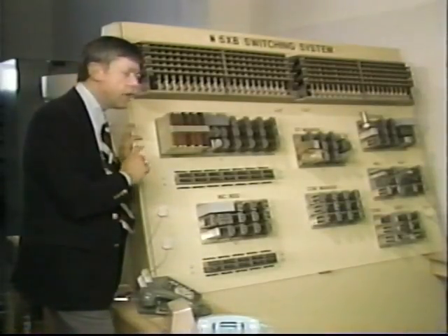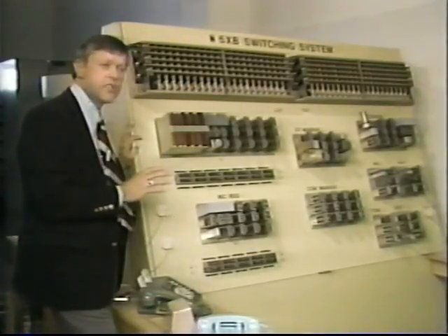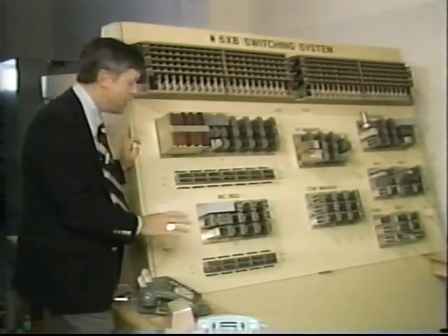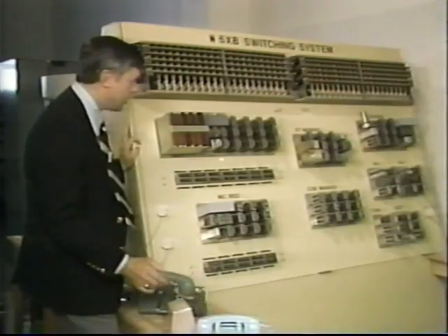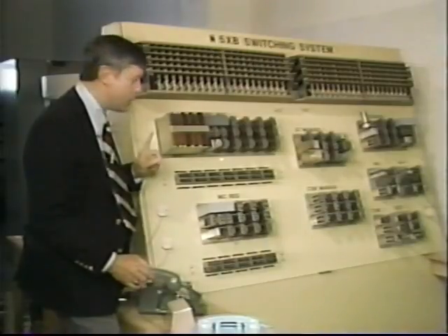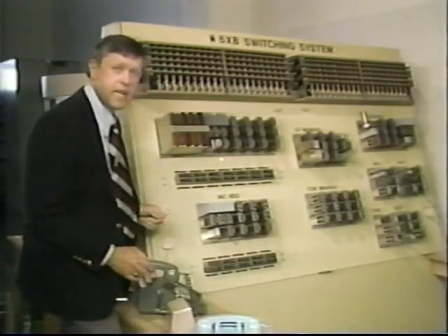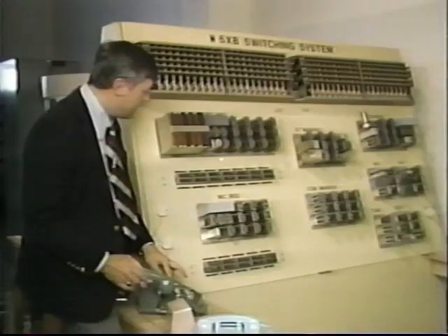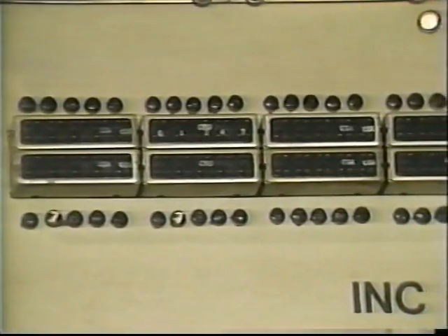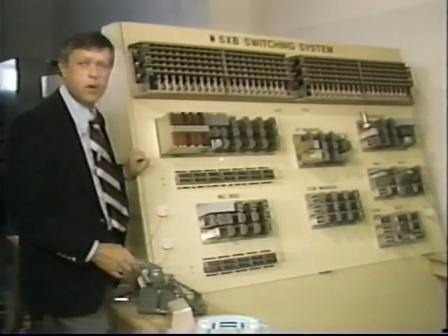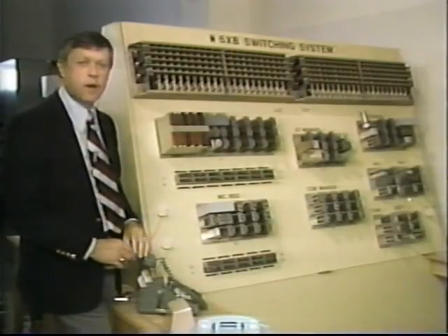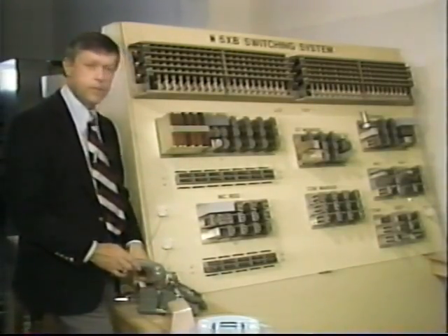Now, this is our sample crossbar switching system. What you're going to see is probably a little too fast to show really happen on videotape, but when the telephone goes off hook here, this originating register gives dial tone and says, hey, I'm ready to receive the number. And you can see there's a light on here indicating that. Now, we'll dial the number, and as we dial the number, it's being picked up by the register and held. Once the entire number is in the register, it switches through the crossbar system and the other phone starts ringing.